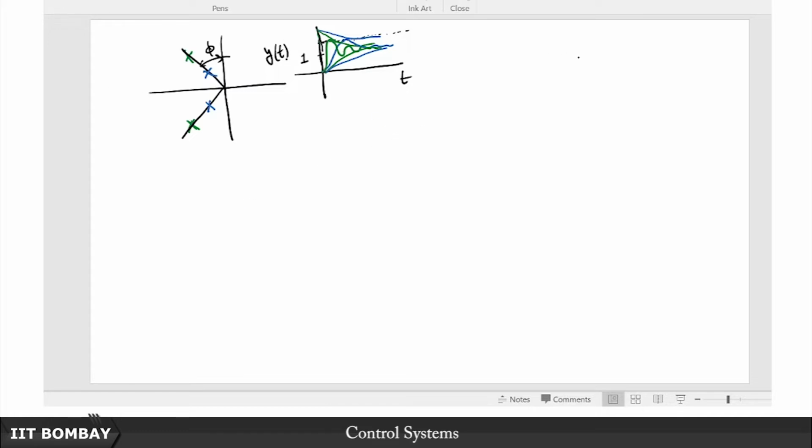What about the scenario, let's say, when you have two poles or two pairs of poles having the same settling time, which is to say the same real part of the pole? Immediately, as we've discussed in the previous case, you'll see that they share the same envelope.